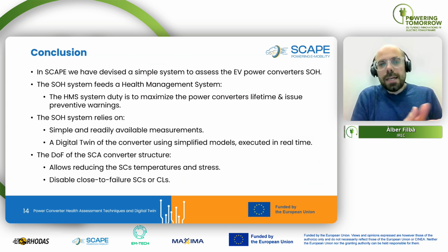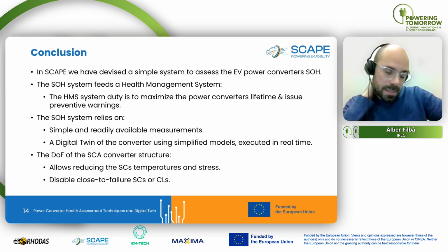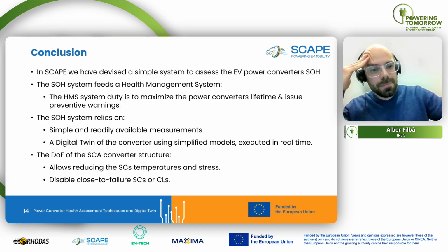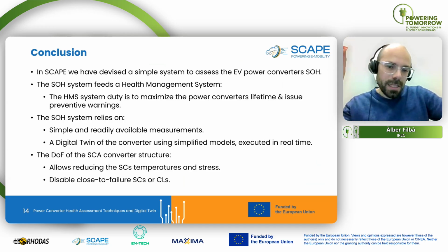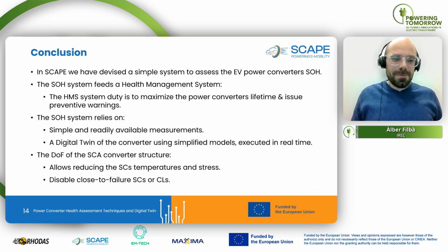In conclusion, in SCAPE, we have devised a simple system to assess the electric vehicle power converter state of health. These SOH assessment variables are fed to the health management system in order to maximize the converter's lifetime and issue predictive maintenance warnings. The SOH system relies on very simple and readily available measurements, so no need for complicated measurements such as the on-state voltage of the MOSFET or the junction temperature. These are very nice, but very hard to implement.